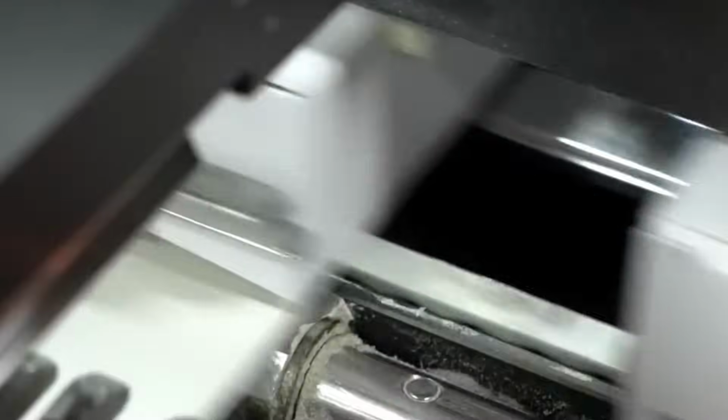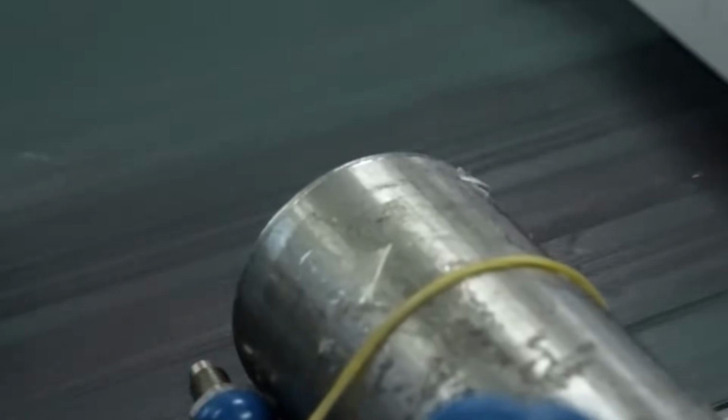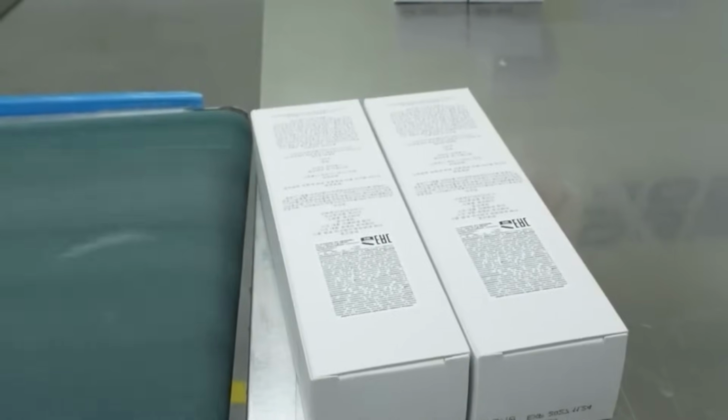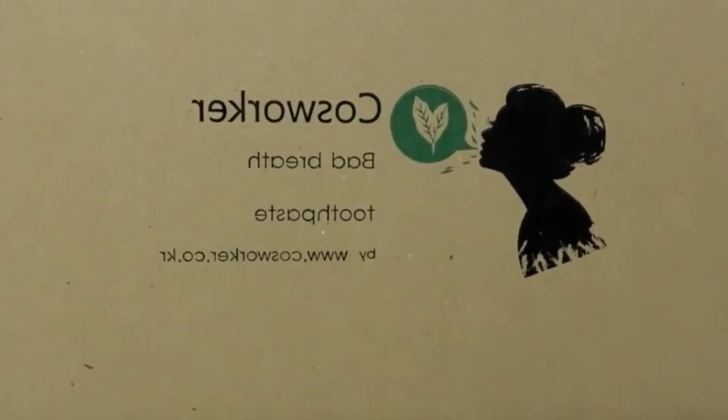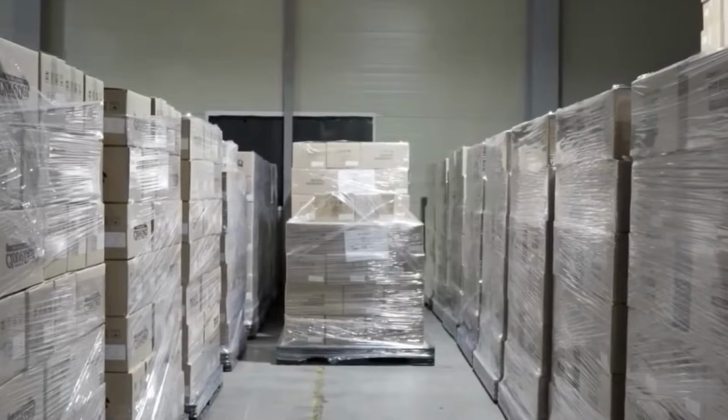The homogenized toothpaste is filtered through stainless steel mesh screens, typically 80 to 120 mesh size, to remove any foreign particles or unblended residue. The product is discharged into vacuum-holding tanks equipped with slow-speed agitators to maintain consistency while awaiting packaging.